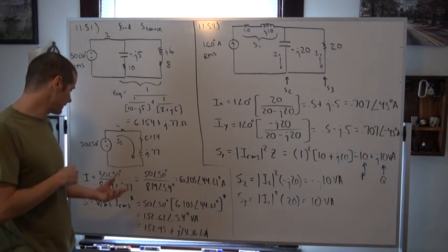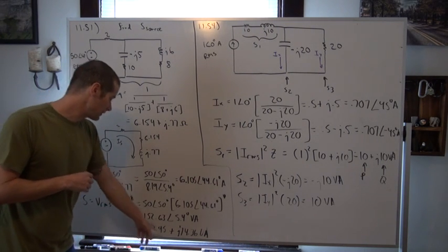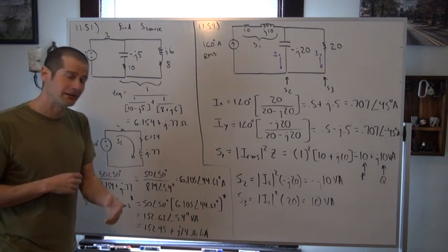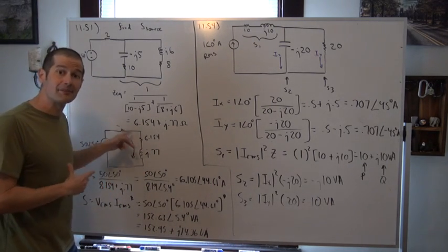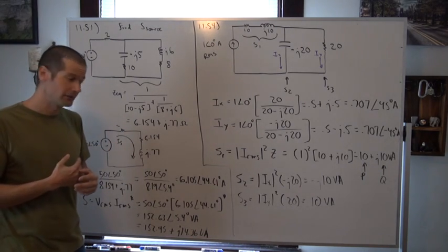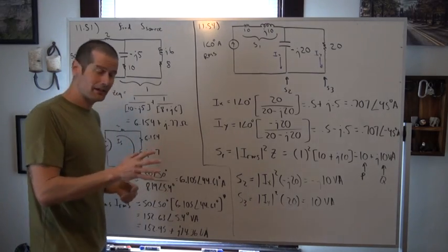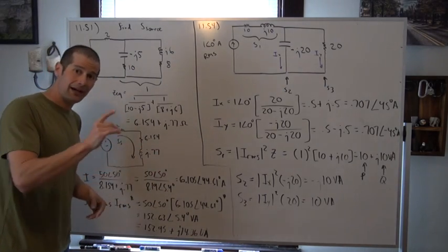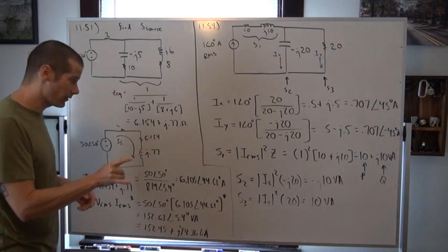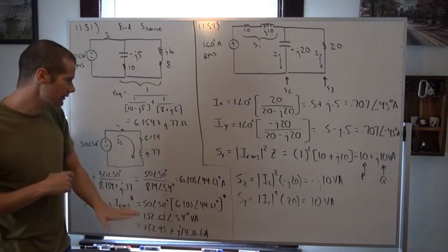Essentially here, guys, this is pretty cool in a way, because what we're actually seeing here is that the positive reactive power is indicative of what we already know as being a mostly inductive circuit. And one thing I also want to make sure we all understand is that because it's an inductive current, that current needs to lag behind the voltage from the source. And sure enough, it does. It only lags just by a little bit.